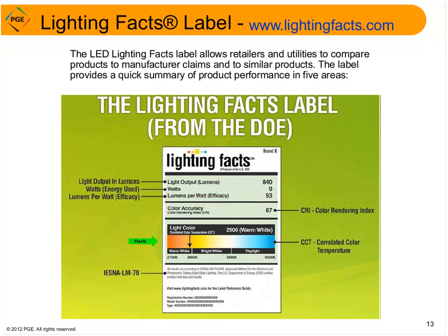Your CCT, correlated color temperature, measures the light color of the light source. Cool colors are going to have a higher Kelvin temperature, say between 3600 and 5500 K, or perhaps higher. Warm colors have lower color temperature numbers, 2700 to 3000 K, very common. Cool white light is usually better for visual tasks, while warm white light is usually better, for instance, for living spaces because it casts a more appealing light on skin and clothing.